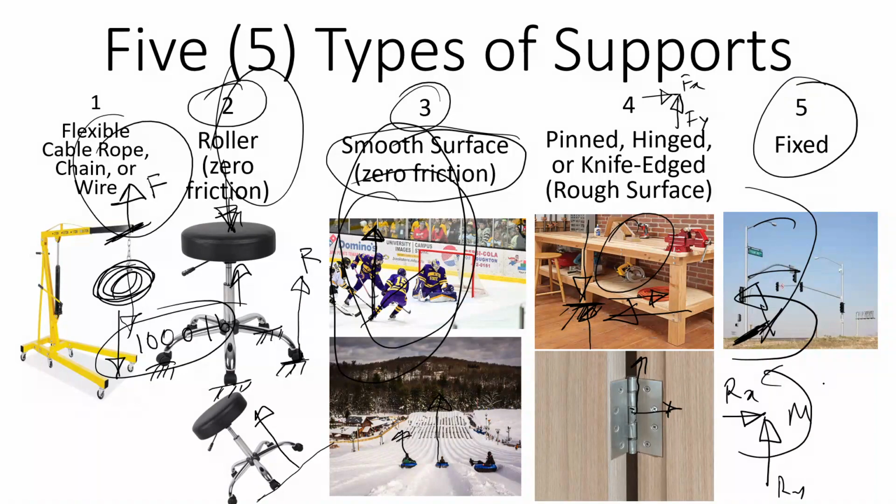One note: regardless of the direction that you think this reaction will have, you always assume the positive direction. As soon as you release it, you try to balance the body. The balancing would always be: X direction positive, Y direction upward positive, and counterclockwise positive.